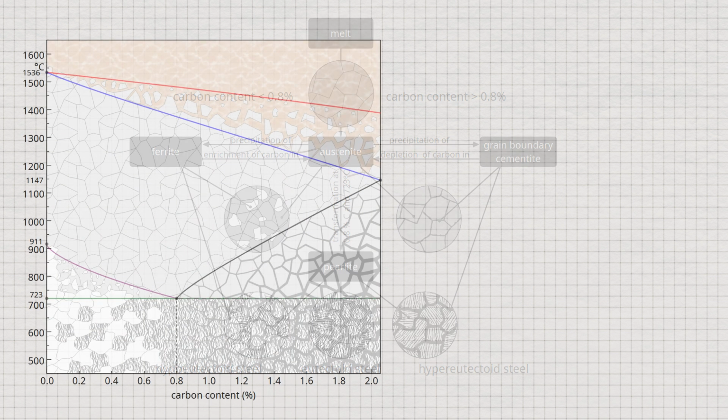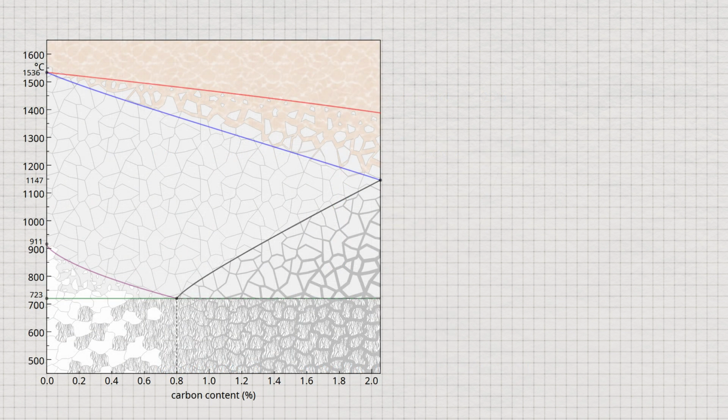In principle, the determination of the microstructural fractions of steels is carried out in the same way as for solid solution or eutectic alloys by using the lever rule. The lever arms must always be drawn up to the corresponding microstructure or phase boundaries. In the following, the microstructure fractions at different temperatures are determined for a hypereutectoid and a hypoeutectoid steel.